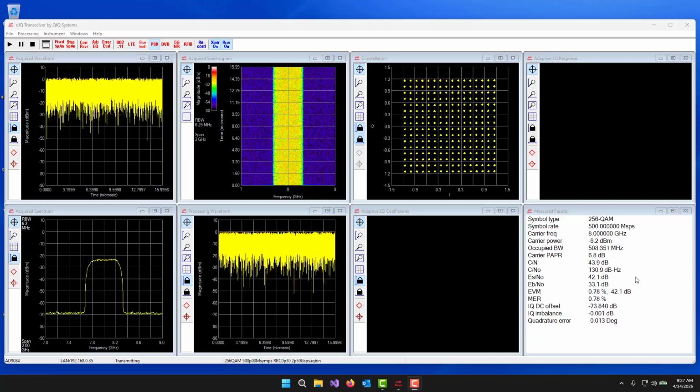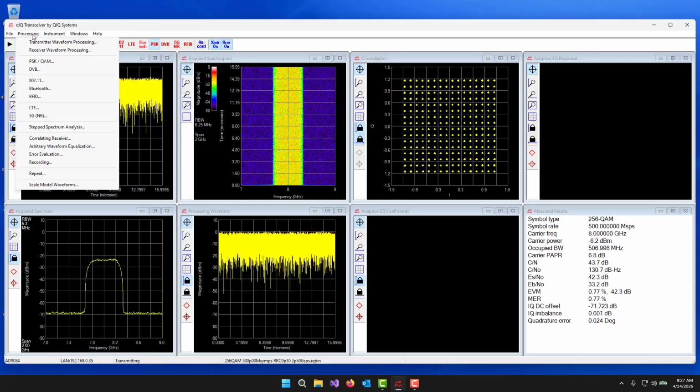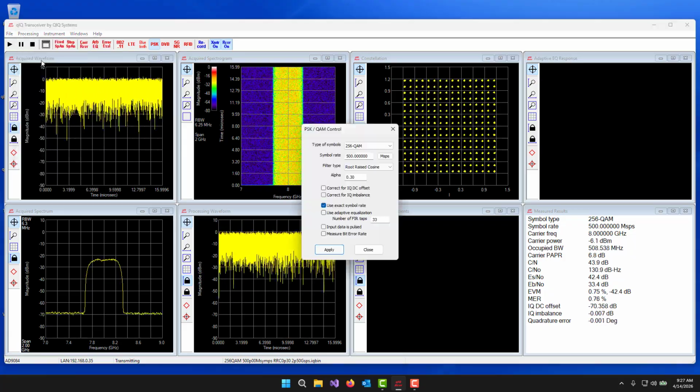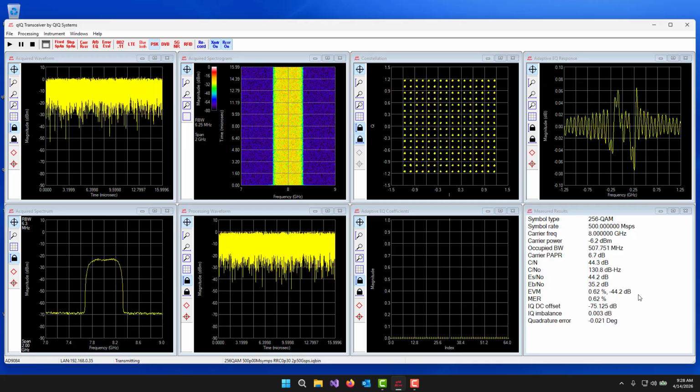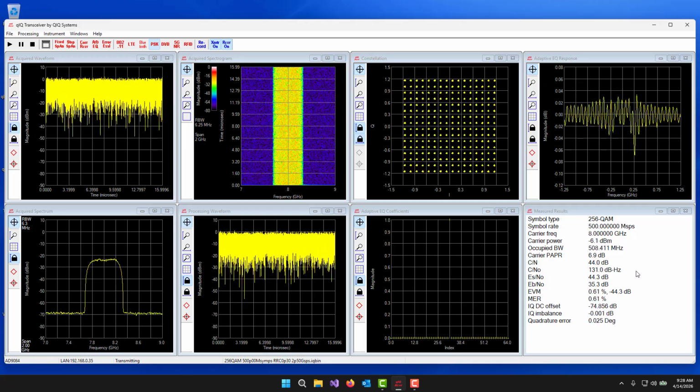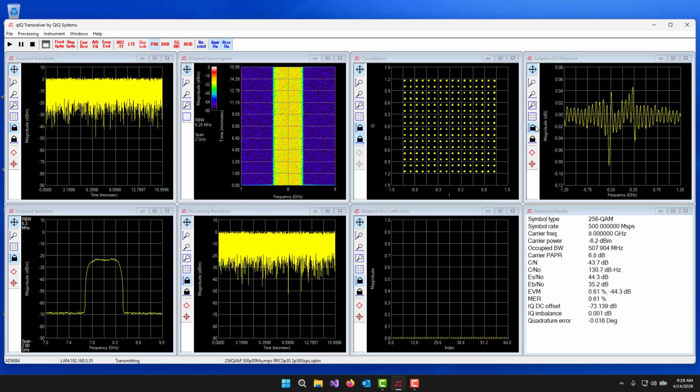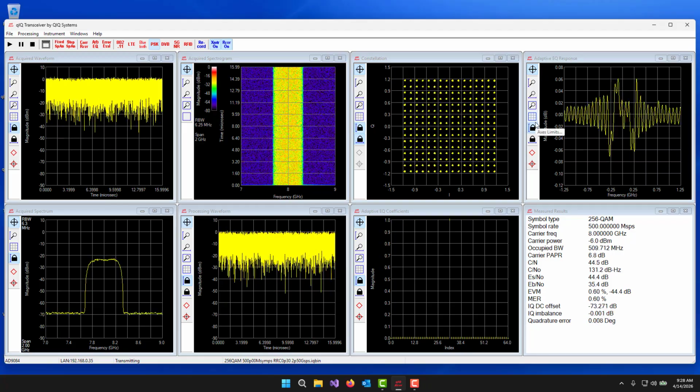Now we're applying it to the data, and it helps a lot, but we can still add adaptive equalization on top of it. So let's go in here, let's turn on our adaptive equalization at 65 taps and see we gained a few more dB by doing this. Stop this from hopping around so much.